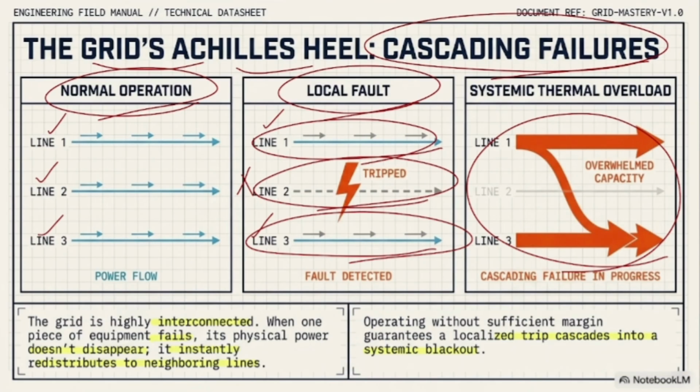But when the next one feels that pressure, that system's protection is also going to be activated. So imagine this kind of problem, which we call cascading failures, happening side by side, and we end up with massive blackouts. It means that your system is down, nothing works, and after that you have to find the problem, solve it, then restart and move everything back to normal.